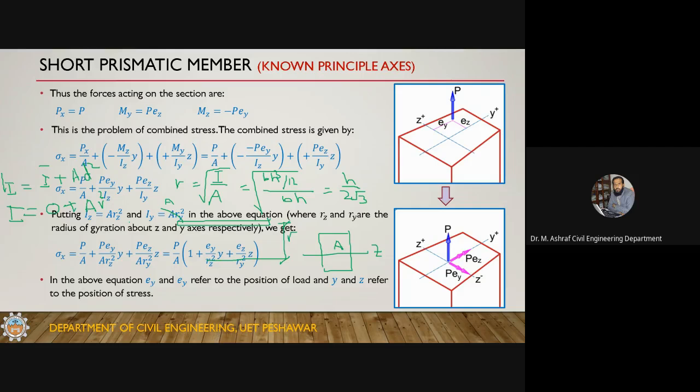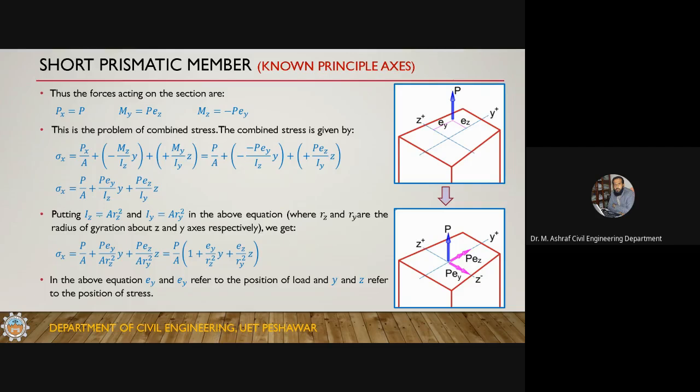This is the same equation. So you can write the moment of inertia in this form also, where r is the radius of gyration, and this is just a mathematical number. It has no physical distance, like from this point up to this point. This is a number, just like the moment of inertia, just like the cross-section area. The radius of gyration is a number whose magnitude can be calculated as the square root of I by A.